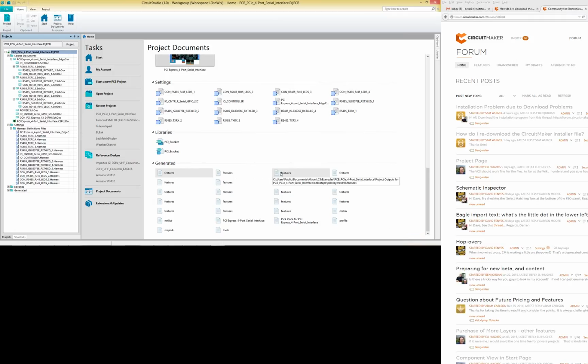So some users occasionally may call up and say, my fabricator doesn't know what to do with all these files I sent them on a thumb drive, and it's just because the fabricator's too lazy to recognize that it's just unzipped already, because the CAM software Genesis made by Valor that the fabricators use in the factory for making the PCB, when they say open an ODB++, typically it's looking for a .tgz file.